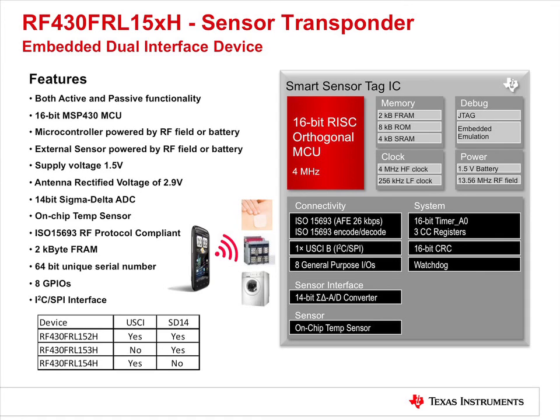The device can be used for batteryless operation completely powered out of the RF field, harvesting the energy from the communicating reader device, or if the device is used for a data logging application, it can be used with a single cell 1.5 volt battery. Intelligent power management, including an RF controlled battery switch, ensures long battery life even if the finished product will be placed for months onto a shelf with an installed battery.